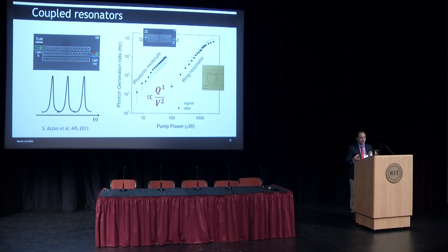crystal system. Now, I'm not saying that in the short term you have to think about photonic crystal systems, because this is never going to work with a foundry. But in the long term, we have to remember that there is no way to get a better Q over V than in a photonic crystal cavity, at least at the moment. Certainly not in a ring. So if you want to have a very strong light-matter interaction at the nonlinear level, this is a system that you might want to consider. Not in the short term, maybe 30 years, who knows. In the meantime, we work with rings. We go on with rings.